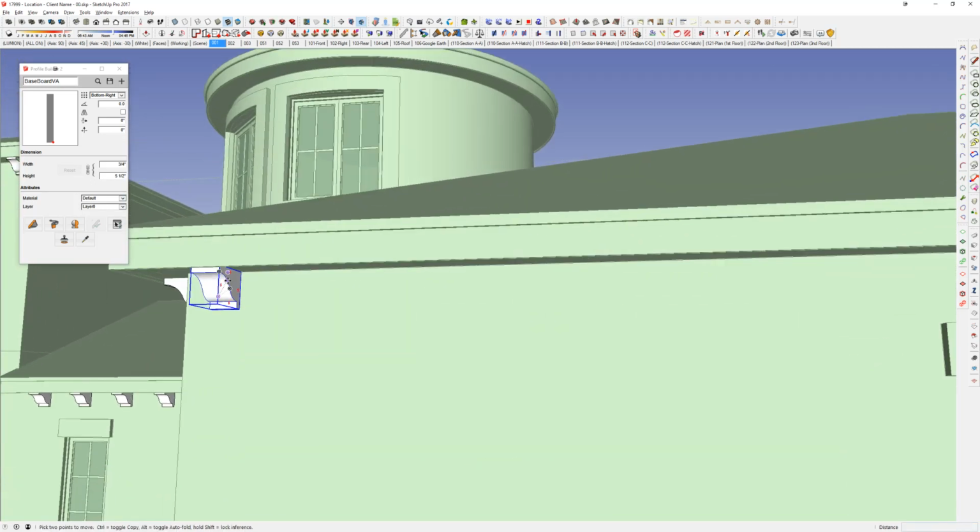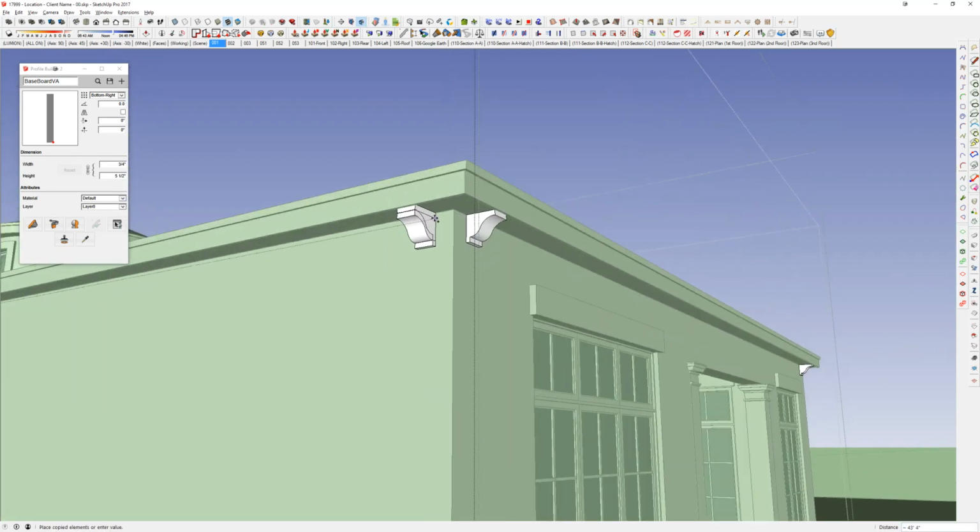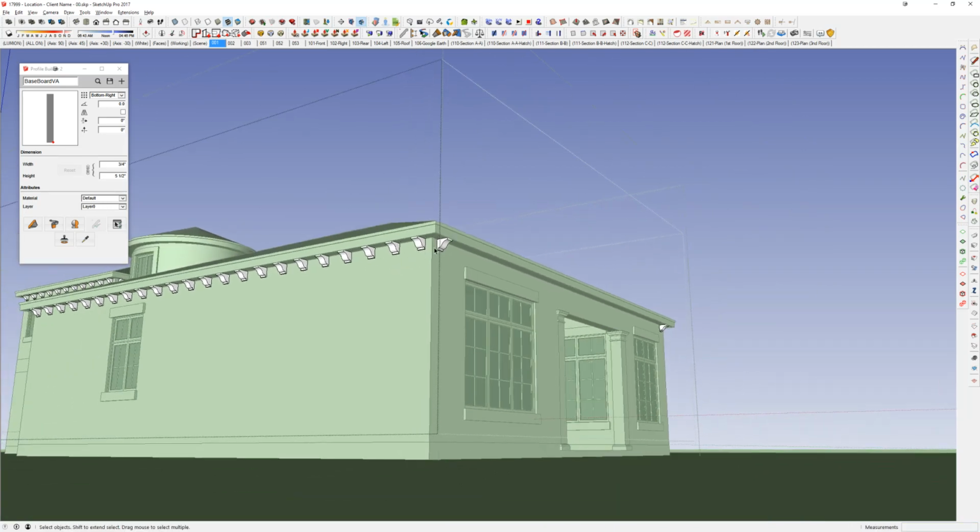And then this one coming across, I'm going to copy this one to here, and you see at the bottom right, looking at my distance, if I lay it over top, it's 43'4", so that divided by 2 is approximately 22. So obviously I'm rounding up to 44 feet, so it's a little less than 2 feet. So it's a judgment call of, do I do 21 or 22? I'll just do 22 divide, and that adds them all in.